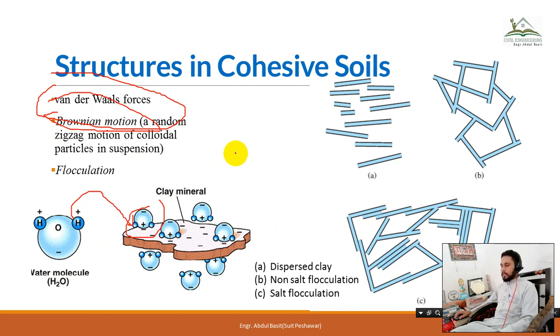Okay, sometimes these clay particles have some other materials inside them, and these materials have flocculation types of properties, and the clay particles are attracted toward those materials. For example, we have a magnesium of positive charge in between the clay particles. So what will happen? The clay particles will surround this magnesium particle, and will form a flocculate. Okay, so the situation will move from this to this.